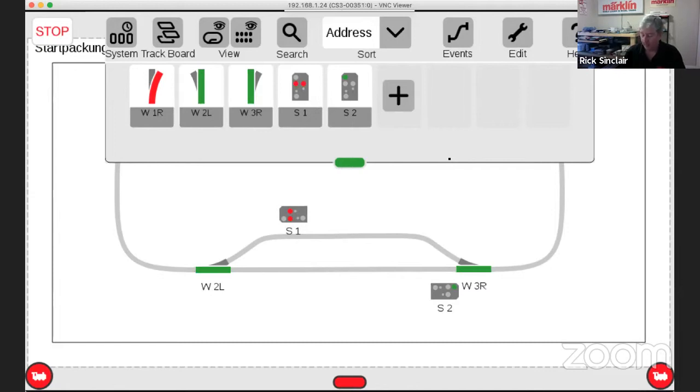I have set the dip switches according to the manual. Always check the manual for the address you want to set your dip switches to. The CS3 does tell you, but it's not hard to find, it'll just be quicker if you go by the table in the manual.